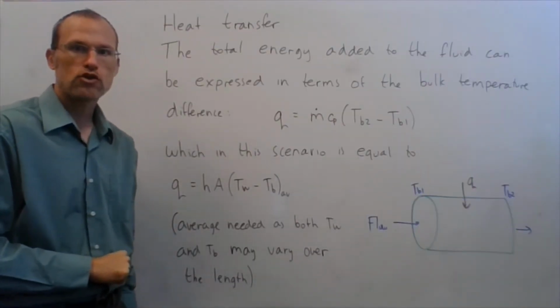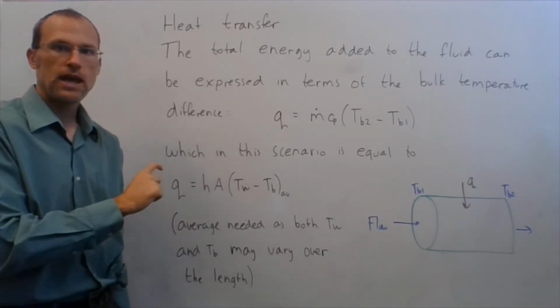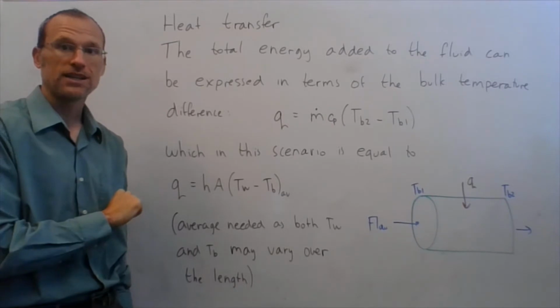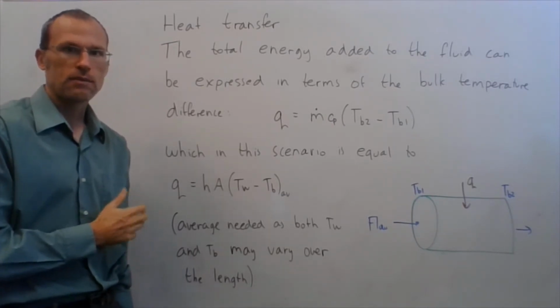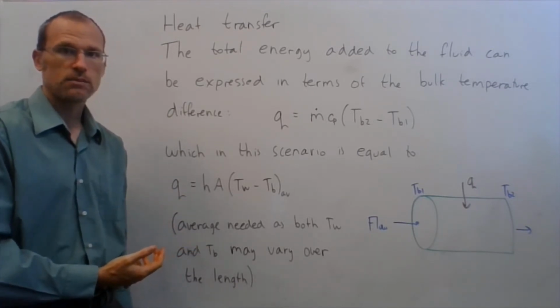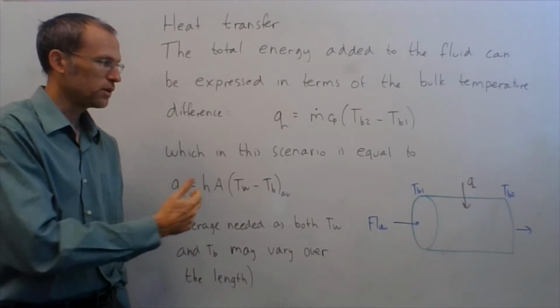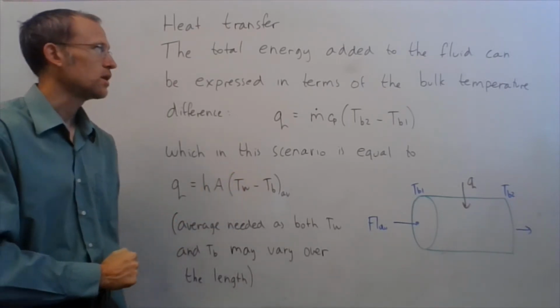So in addition to the energy balance that we did from the fluid being convected through the pipe and the heat being conducted through the pipe wall to find H, we also have to think about the fact that this heat is being transferred into the fluid, and so I'm going to have some temperature difference as my fluid goes through. It's going to be heated up or cooled down.